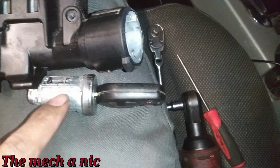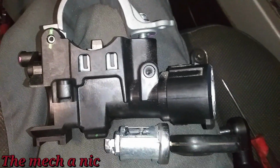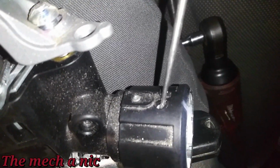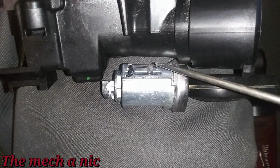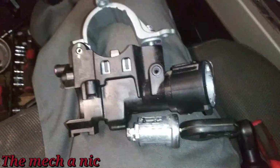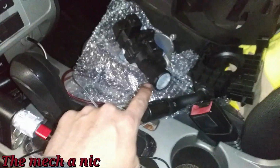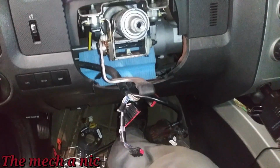In order to remove your cylinder, you have to use the original key, of course. You put the key in it, and you're going to turn it about 3/4 of the way, like you're about to start the car. And then from the top right here, there's going to be an access hole, and you come in here with a pick, and it's going to let you push down on this little button right here. But you can only access or push down on this button with the key in the correct position. So you absolutely need the key in order to do this. So at this point, we got the piece off, and it's just a matter of put the cylinder in the new piece, put it on the car, put the new bolt on it, and start to put everything back together.